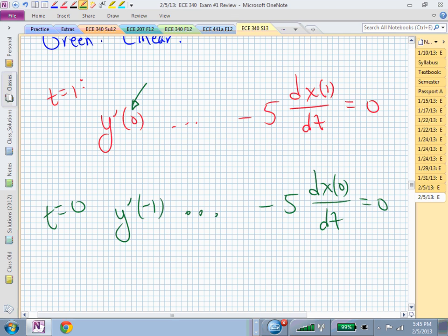And now you have an input in the future relative to this output driving this output. And that's the same relationship that you had up here. Does that make sense? So it really doesn't matter what you pick for t, just as long as you think through what you've got. So this says that you now have a non-causal system. Question?